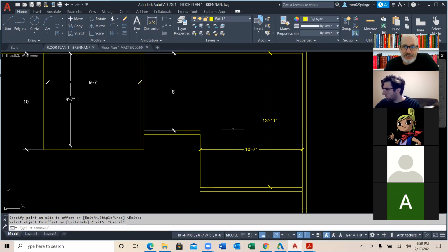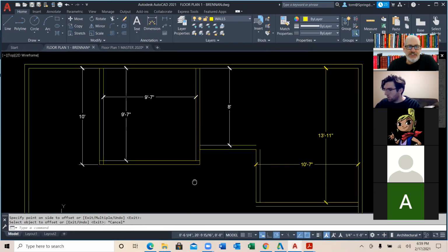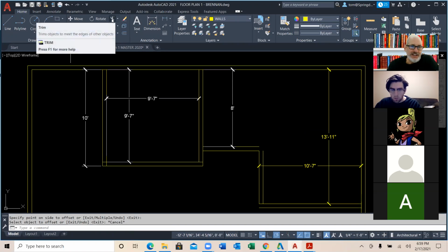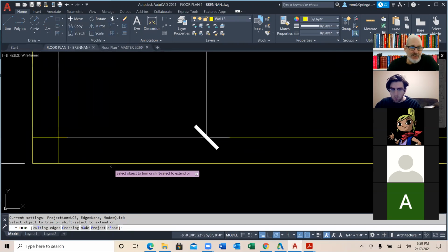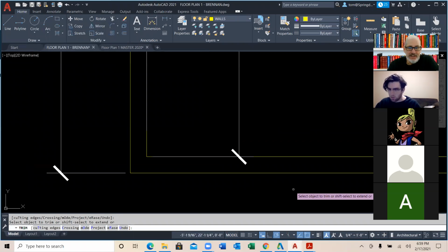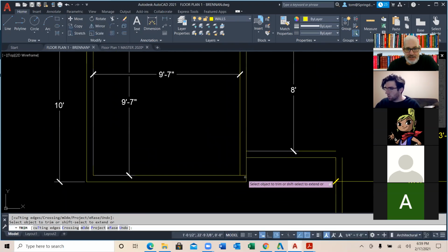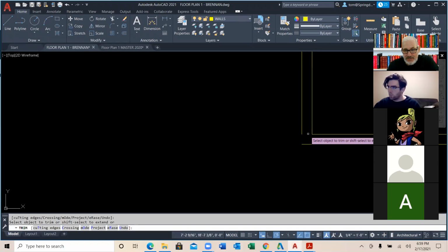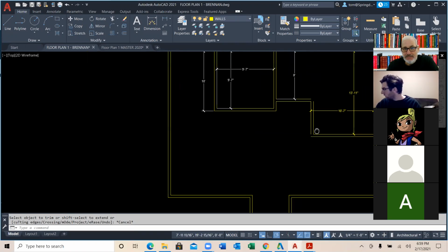Now I'm going to show you a quick trick for fixing all these corners, and that's the trim command. I went to the trim command in the bracket, but if I start the trim command right here, watch what it does. It looks like a pair of scissors. When you click on it, everything is now game, and you can begin getting rid of things that you don't want. This is how you'd go through here and clean up these corners, like this and so forth. So that's how we do that. I could also go right to here and do this, and we'd make that happen.